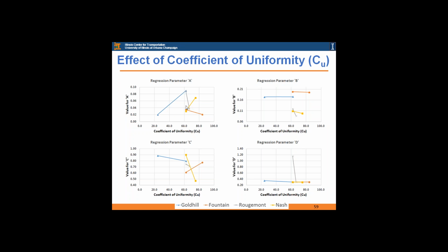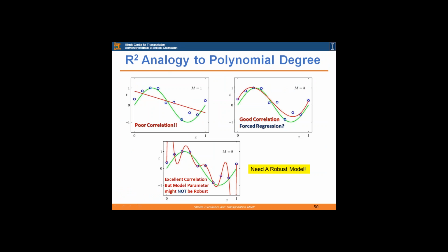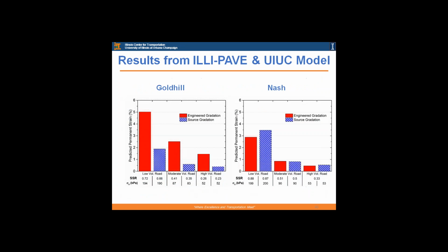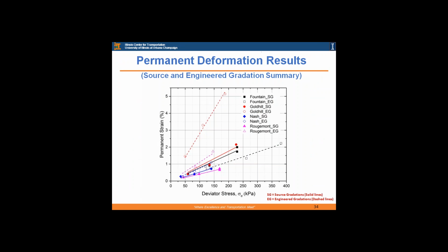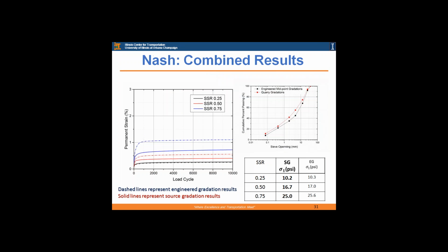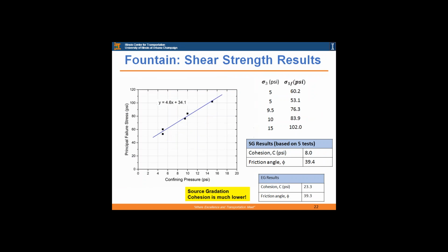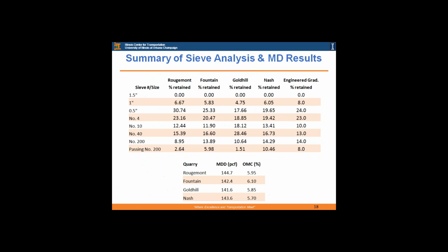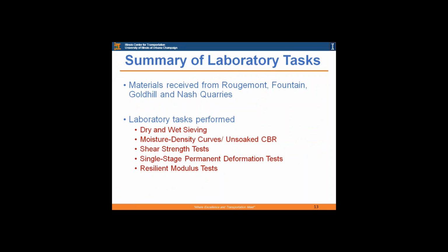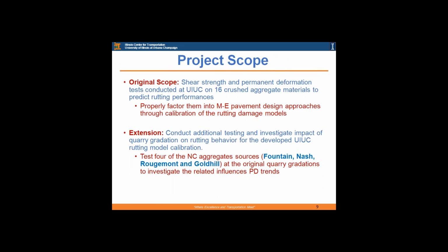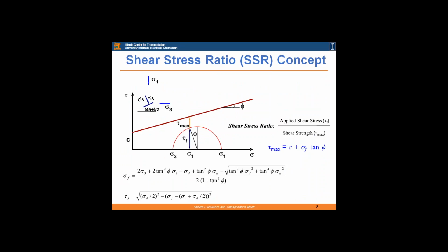All right, perfect. But then, what is actually going on in that shear plane of the sample when the sample is about to break? The shear strength mobilized on that plane, that's the highest shear stress, that's supposed to be reaching 1, right? That's the ratio where, as you go over 0.6, 0.7, you start to accumulate permanent deformation at a much higher rate. This is true for all materials, subgrade soils, asphalt, concrete, the same.